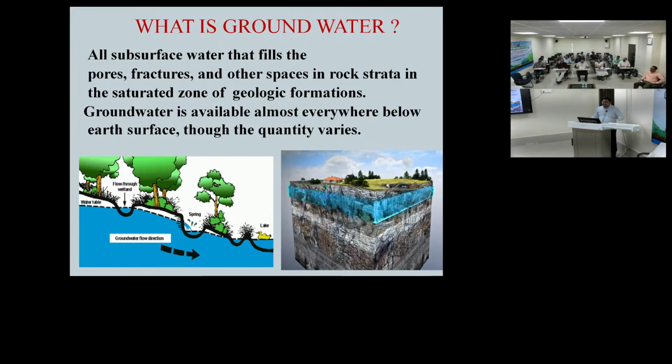But if you go to the upper Assam side, even Sibsagar, Dibrugarh, Dhemaji, you need not worry for anything, because you dig a well, 40-50 meters, you will get ample amount of water, because it is already saturated. Those are sediments and pore spaces, and it is a continuous sedimentation. I'll come to it. There are confined and unconfined aquifer systems. That is what groundwater means.